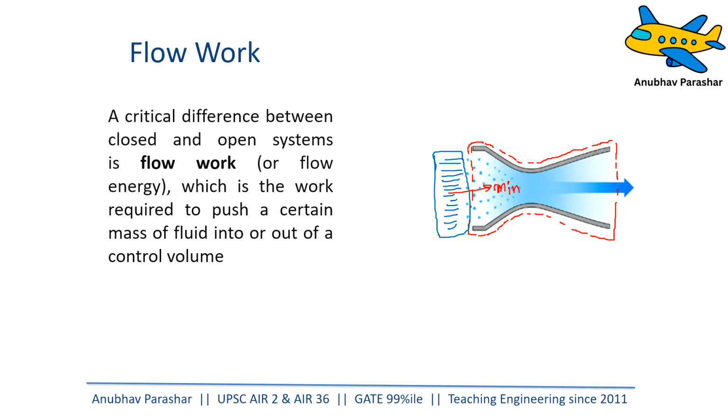Now, you see the control volume is already full with particles. It already contains certain mass. So for this piece of mass to get inside, it has to be pushed inside. It cannot simply go. The control volume is not empty, so it cannot simply go. It is full. It also has some pressure. So it has to be pushed to get inside. Now, who is going to push this mass element? Definitely the fluid which is behind this fluid is going to push it. Now, when it pushes, some amount of work has been done.